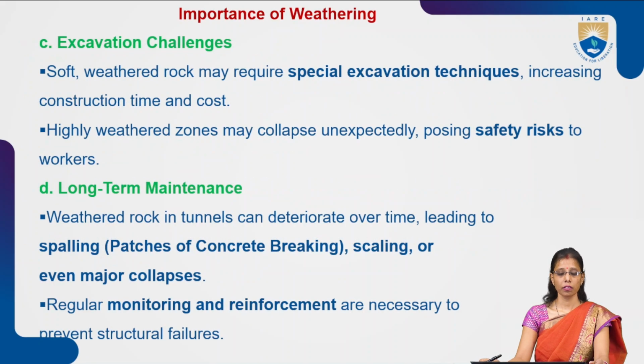Now, excavation challenges. What are the excavation challenges here? Soft weathered rock may require special excavation. When you talk about the excavation process in tunneling, weathered rock may require special excavation techniques, increasing the construction time and cost. Now, highly weathered zones may collapse unexpectedly, posing a safety risk to the workers, whoever is working over there. So there is a risk of collapse of the tunnel.